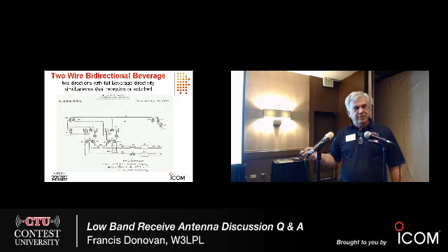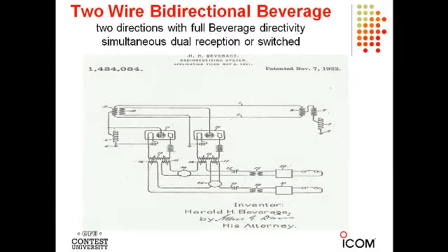But in the opposite direction, the two wires are actually being used as a transmission line to bring the signal back from the far end. So there it does matter. And on 160 meters, I don't think you'd want the spacing to be more than about 2 feet. That's probably the maximum. The minimum, there is no minimum. It can be a twin lead wire and it would work fine. So anything from a fraction of an inch to 24 inches is fine for the transmission line performance requirement for this antenna.